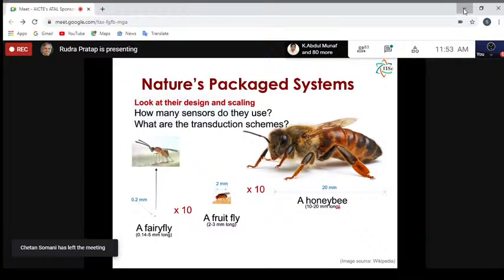Now, if you know that the force you applied and the deflection are related to each other in this form, then the force divided by the deflection gives you the stiffness, right? So you immediately can find out what the stiffness is. And if you know the stiffness and you know the mass, then if it oscillates, you know its natural frequency of oscillation as well.